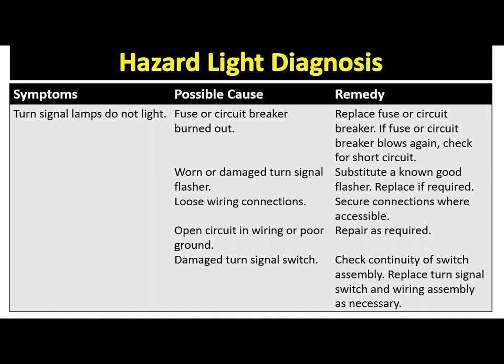You have to find that out somewhere along the wire harness to find the short circuit, some damaged wire, some damaged terminal, something like that. Then substitute a known good flasher, replace if required. You can find out if the flasher is good or not: when you energize the flasher connected to the battery, you will hear a tick-tocking sound inside the flasher.